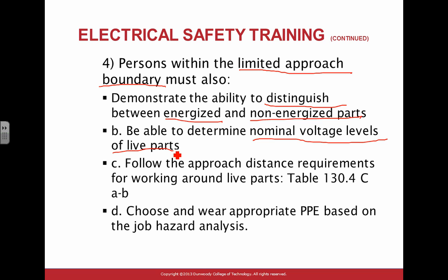This is very, very important, guys. Before verifying the absence of hot, what voltage am I looking for? To do that, you have to have an understanding of the typical control voltages used for this equipment. Am I having 24 volt, or 26 volt when my system is supposed to be 24 nominal? There's a little fluctuation, it always fluctuates. Or am I looking for 480?